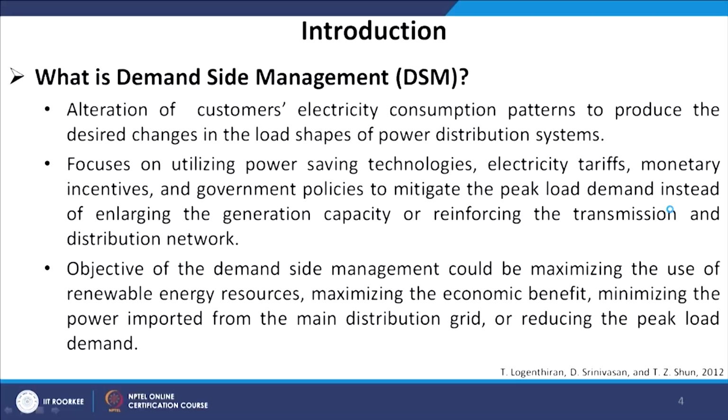Similarly, if you can optimally utilize your renewable sources and avoid drawing maximum power through your distribution system, that itself is a local optimization for your smart grid. Because you are not drawing maximum power from the transmission system through the distribution system, you can certainly reduce the peak expectations from the utility side. So, the peak demand of the utility can be reduced further if you do not draw energy from the main grid to your low voltage grid, if it can be locally optimally managed.